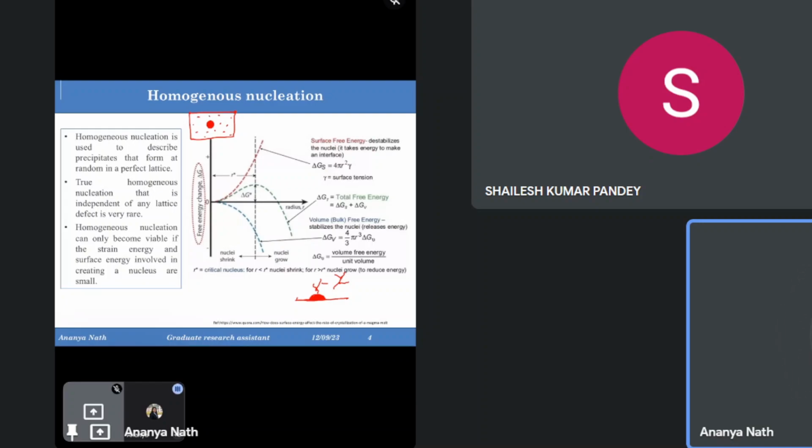But you can imagine homogeneous nucleation is very rare. It's very tough, because at the same time surface free energy and volume free energy are also acting here. The more the surface free energy increases, it will not let the nucleus get bigger and bigger with time. It will always try to minimize because it's an energy, and we never want any high energy thing. So surface energy will try to restrict the growth. At the same time, the volume free energy will try to expand. With the interaction of the surface free energy and the volume free energy, there will be a tug of war between these two, and as a result a nucleus is formed out of no help of anything.